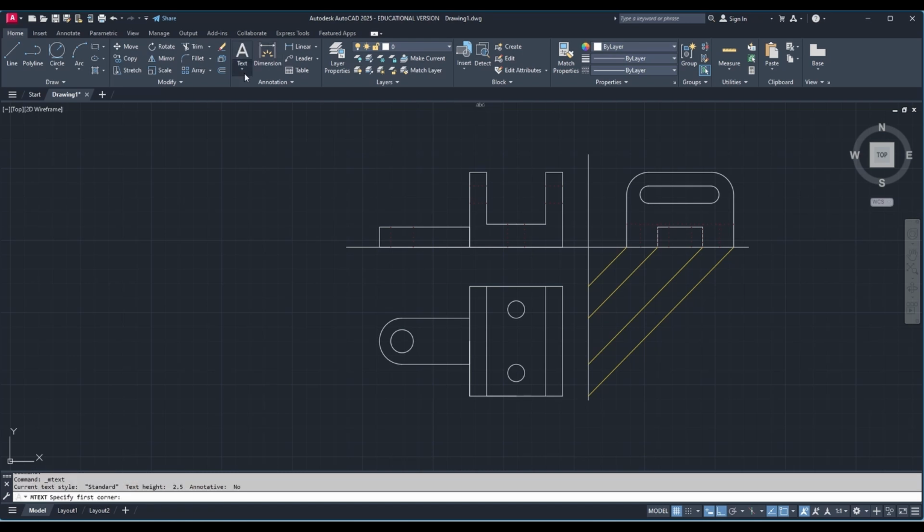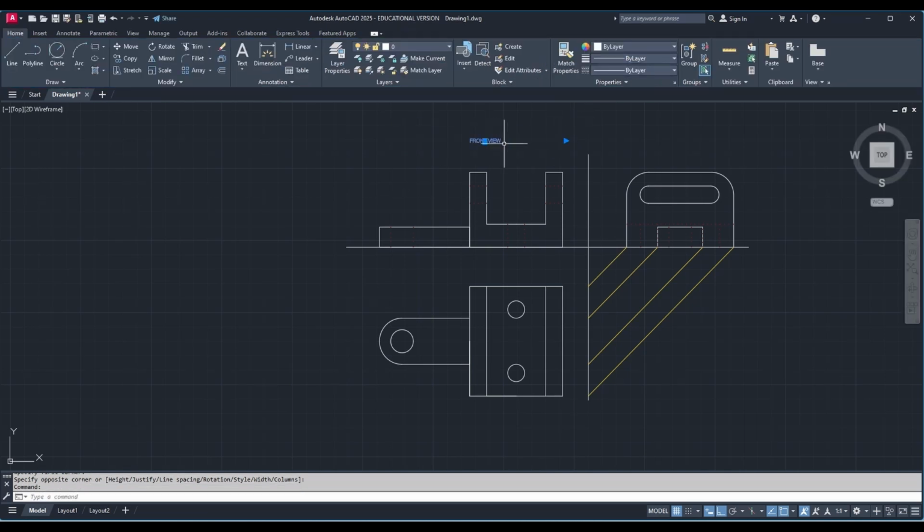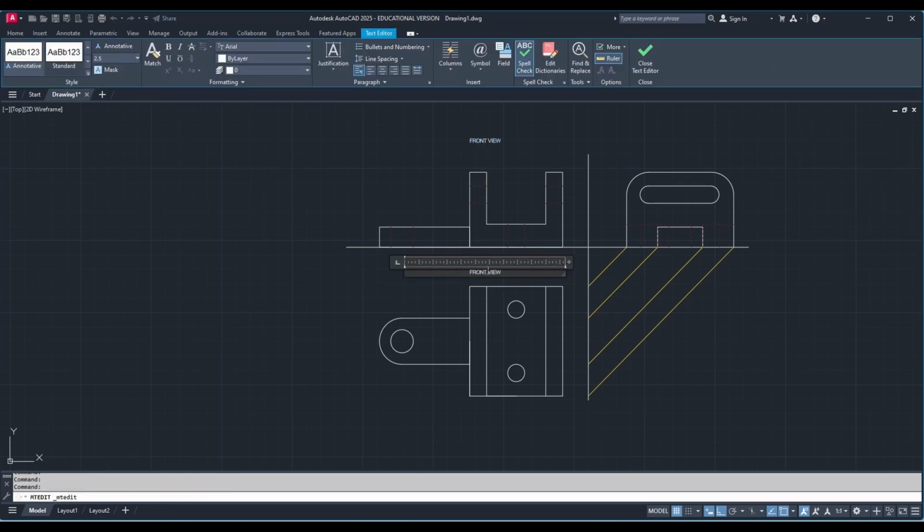Now I am naming the view, which is what is remaining. I'll draw a box. Okay, then I need to change the justification to middle center. Then I will copy it to the other side to get the other naming. So I will select that and take the copy option. I'll copy, hit enter, then move it from that point to here and press escape to complete.